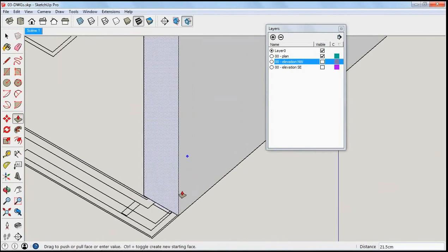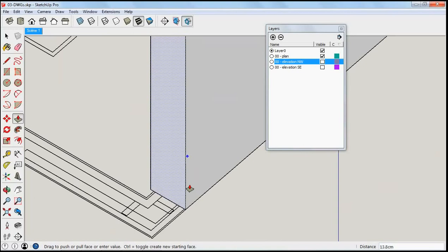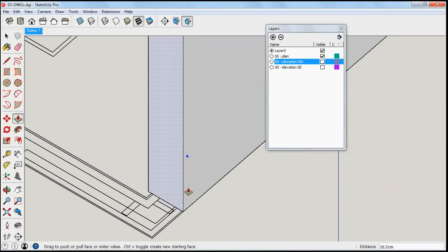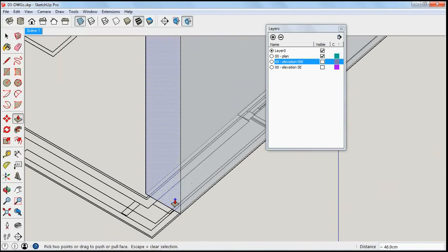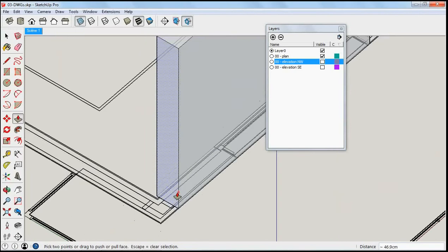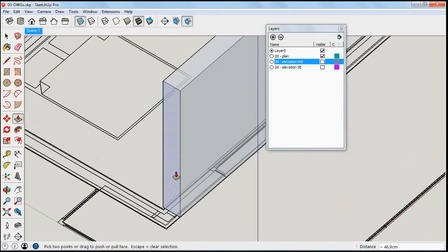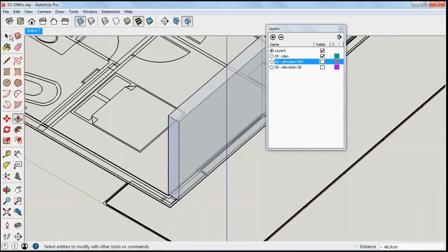See, if you see now, you are not able to see the line underneath. So it's very difficult for me to see the elements. So in that case, what we have to use is the X-ray tool so that we can see the elements and we can snap them. Now I am constructing additional walls using the combination of move and copy.